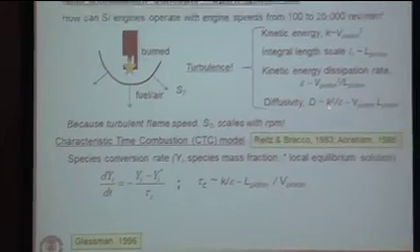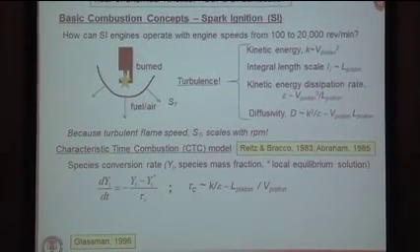The diffusivity, or the rate with which mixing occurs in the engine, is going to be, just borrowing from the kinetic theory of gases, related to a characteristic velocity, which again is the piston velocity, and a characteristic length. If one uses the K-epsilon model, you can relate that to K squared over epsilon.